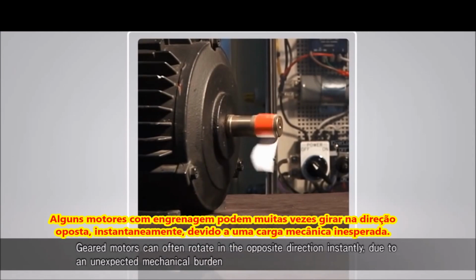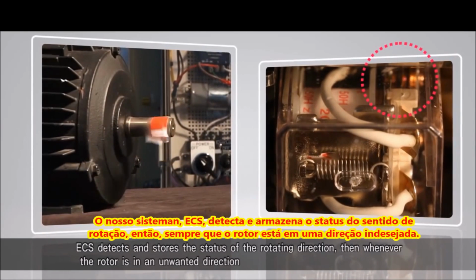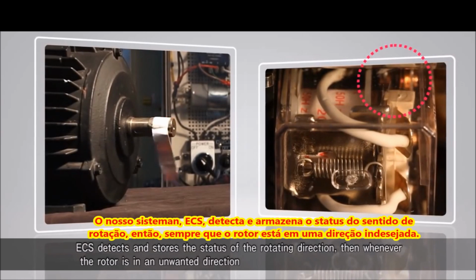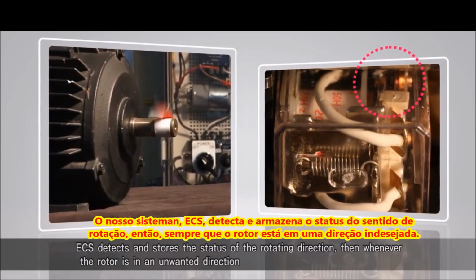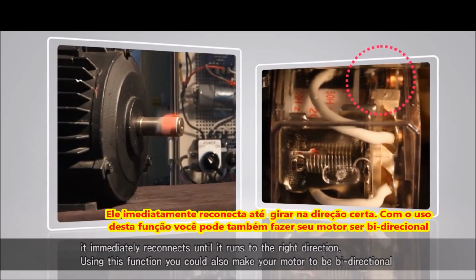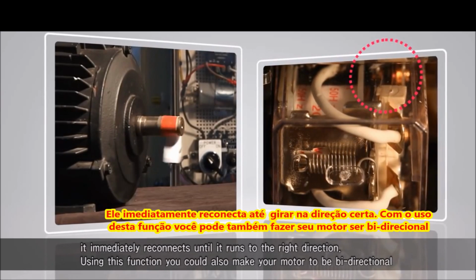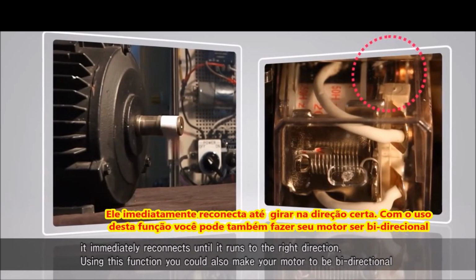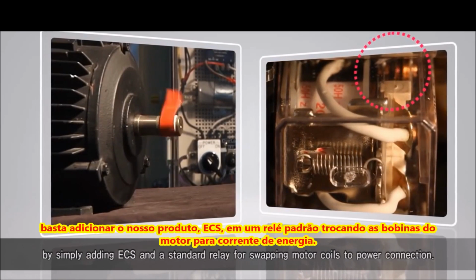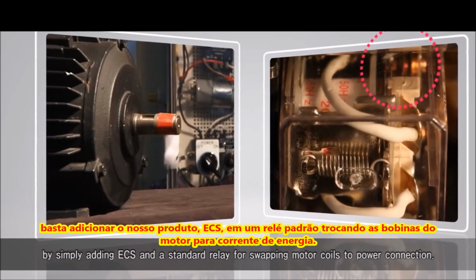Geared motors can often rotate in the opposite direction instantly due to an unexpected mechanical burden. ECS detects and stores the status of the rotating direction. Then, whenever the rotor is in an unwanted direction, it immediately reconnects until it runs in the right direction. Using this function, you could also make your motor bidirectional by simply adding ECS and a standard relay for swapping motor coils to power connection.